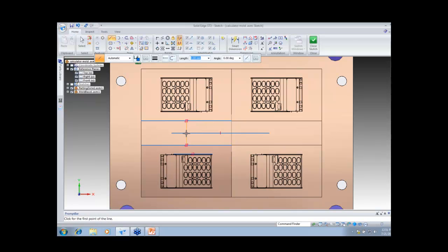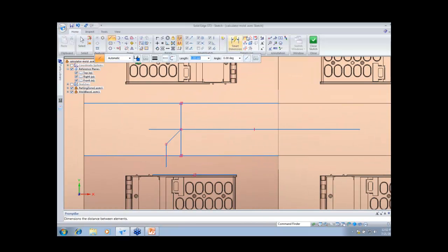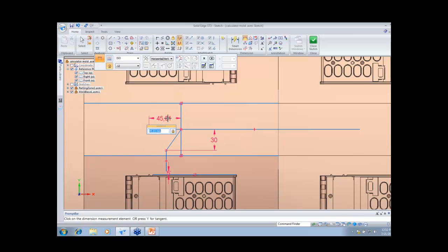Here, I will create an angled injection. I'll say minus angle, and then give it a line here. Everything looks good. Let me put some dimensions on it so that we know how far we are from the port. I select this one, this one. From the port, we want to be at 5 millimeters. And here, let's say 30 and 25. All right, everything looks good.